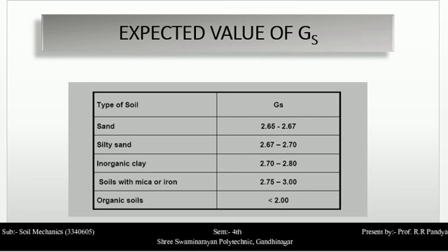For sand, the specific gravity lies between 2.65 to 2.67. For silty sand, the value lies between 2.67 to 2.7. For inorganic clay, it lies between 2.7 to 2.8.